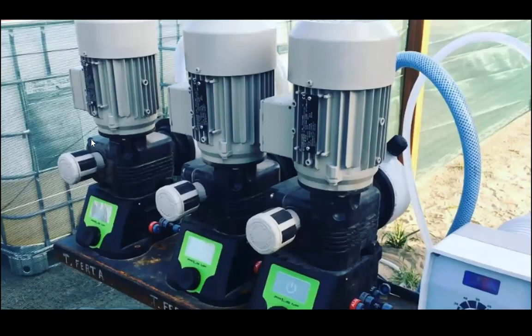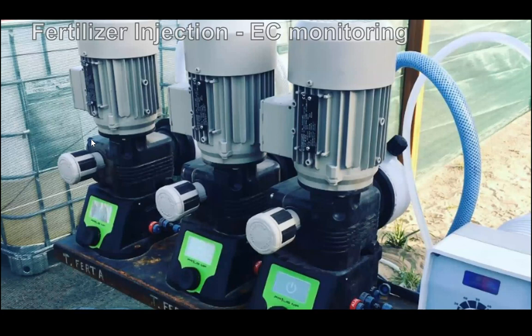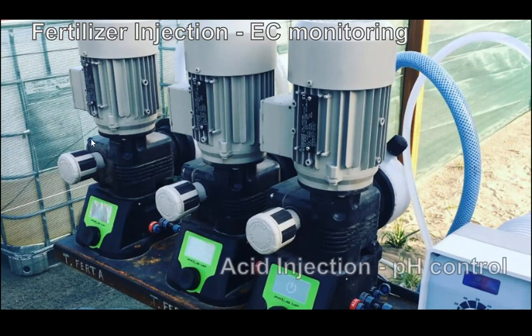We are also involved in the fertilizer injection, monitoring electric conductivity and fertilizer injection, controlling the pumps that inject the fertilizer from the tanks. And acid injection, in case you're using this for pH control, can also be tied into a pH sensor on the pipe and run a control cycle in order to maintain a pH on the water.